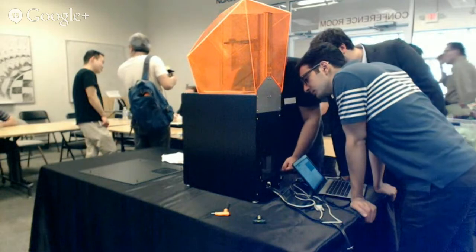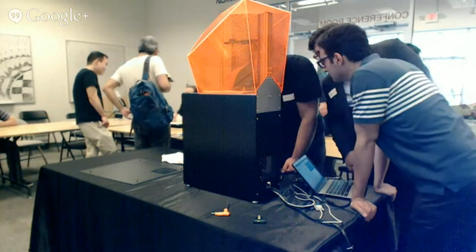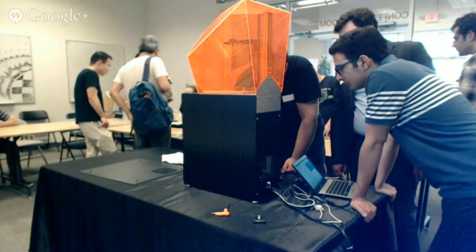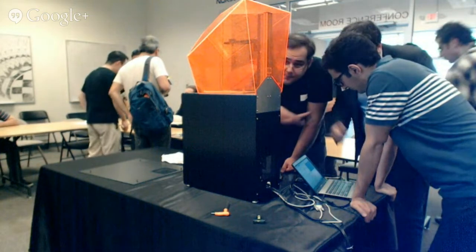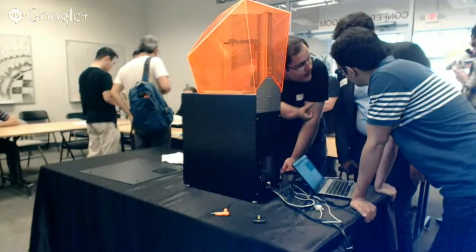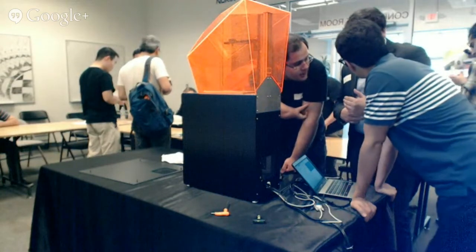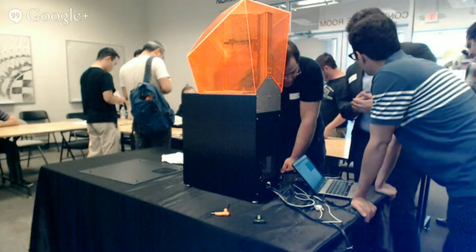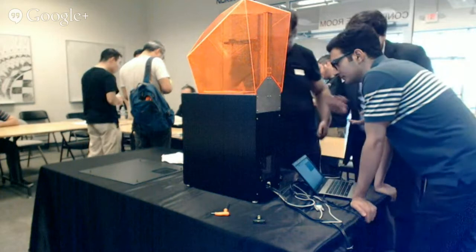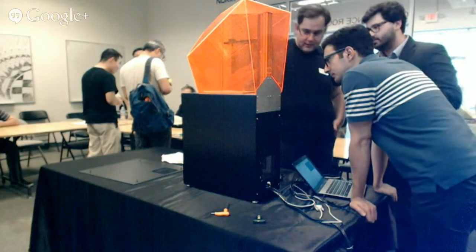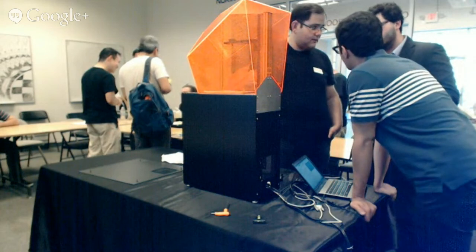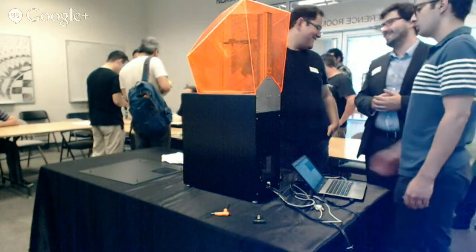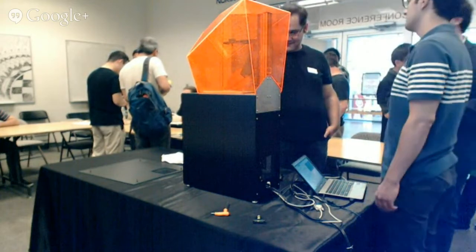With 3D printing for this, you're going to have a really big effect whenever you have a big change in surface area between two layers. And even in this one, you can still see that there's, you can feel that it comes out, right? The wall is fine, and right here, it comes out, right? And that's because that's where the roof comes out. And so the previous layer is just the wall, and then the next layer is the roof. The change in surface area between those two layers is gigantic, right? So it should shrink more, not less, right? It's hard to say. But it creates distortions, right? It'll affect the surface quality of the part.